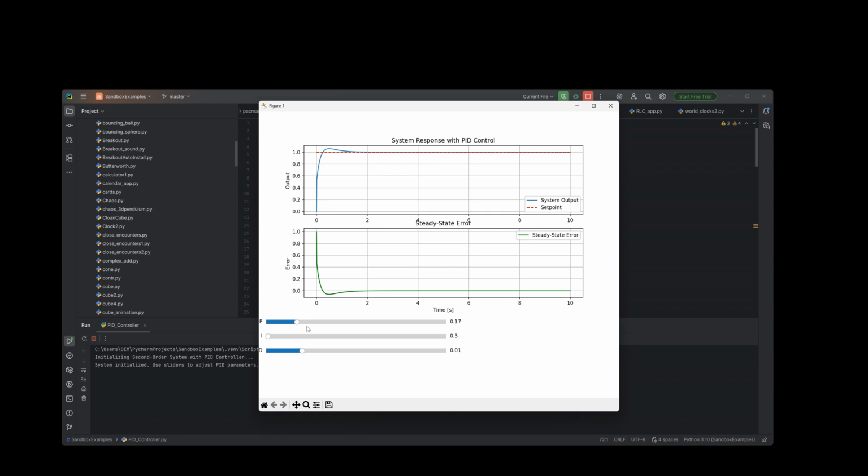Electromechanical systems usually have a structural resonance. Some of the fastest hard disk drives in the world have enormous bandwidths, and the structural resonance stops you from making them wider. There's lots of things, but the structural resonance stops you from getting even higher bandwidths than you'd want. So in real life you can't just put in any PID values you want.